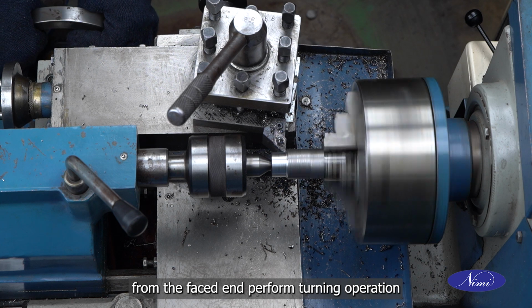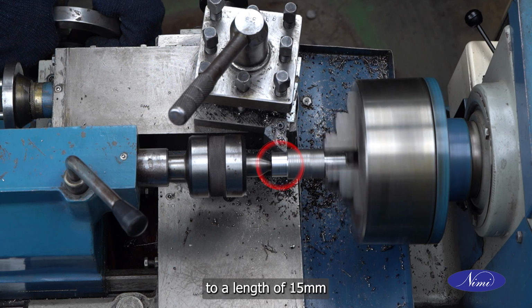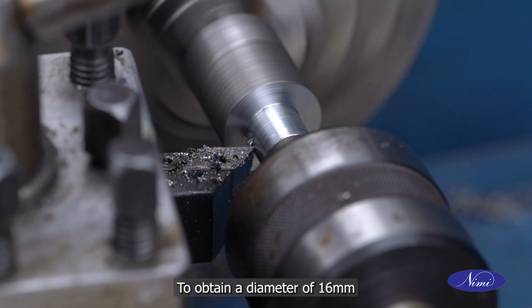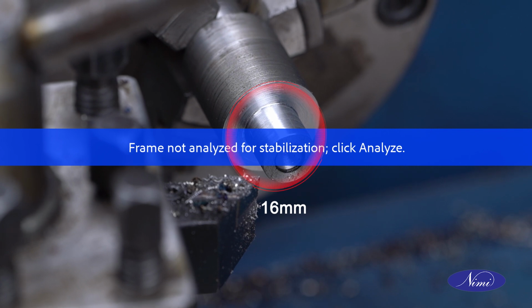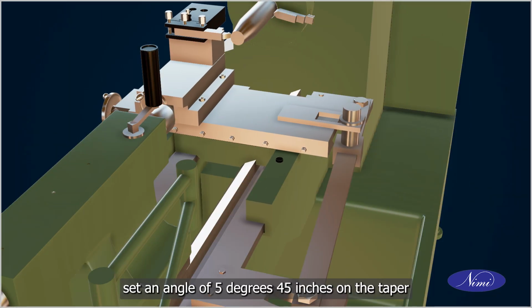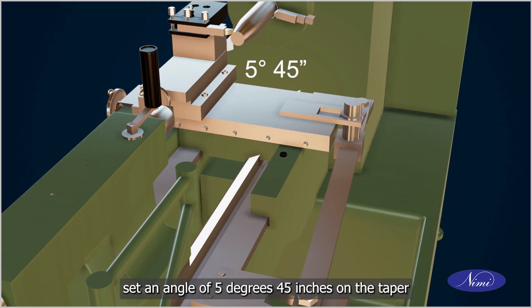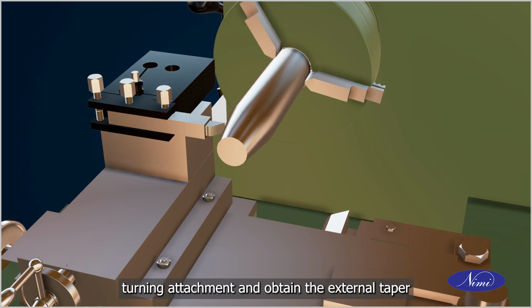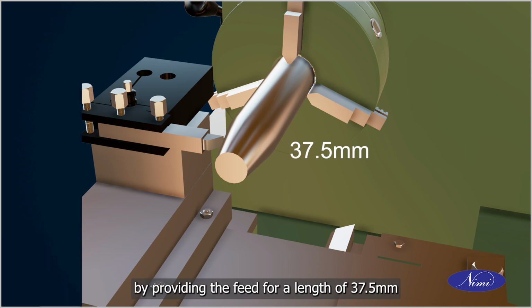From the faced end, perform turning operation to a length of 15 mm to obtain a diameter of 16 mm. Set an angle of 5 degrees 45 minutes on the taper turning attachment and obtain the external taper by providing the feed for a length of 37.5 mm.